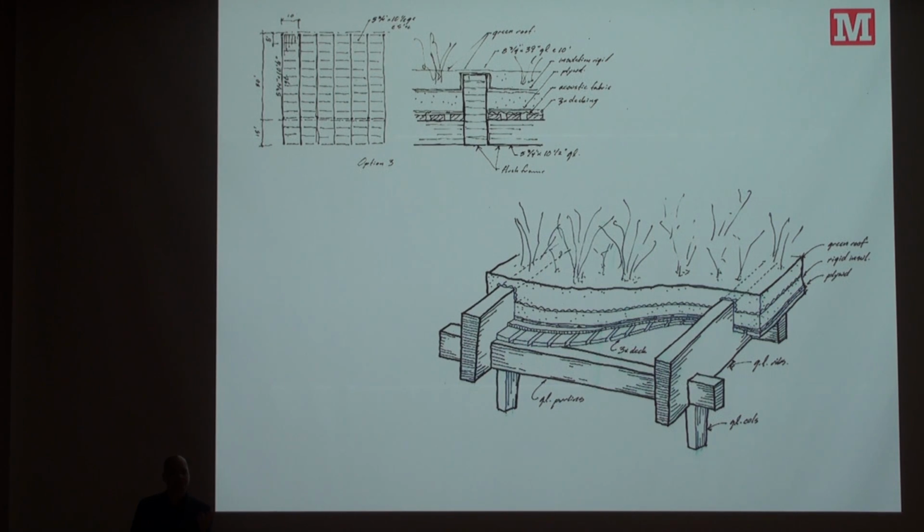So it is both a piece of structure and an architectural ceiling that's been tuned for acoustic absorption and acoustic refraction. And so it's all together, and then we have the insulation and the living roof. And because we want to get this sort of basket expression for the structure below, we had to upturn the ribs because of the span. So this even affects the drainage solution of the building. So it's all tied together.